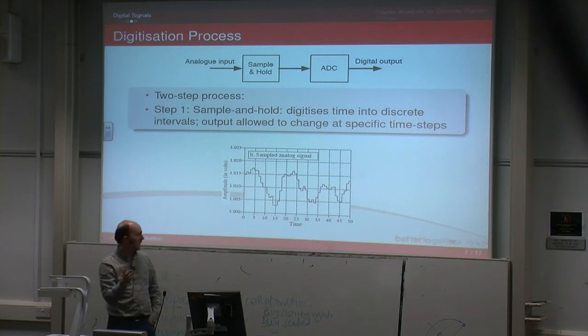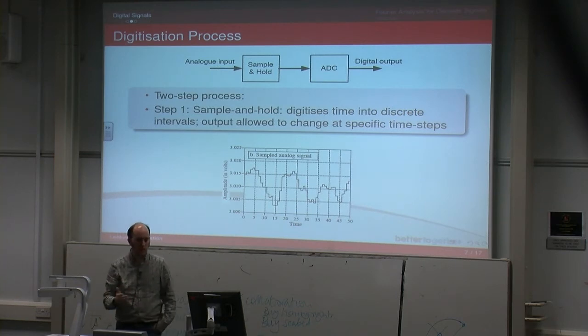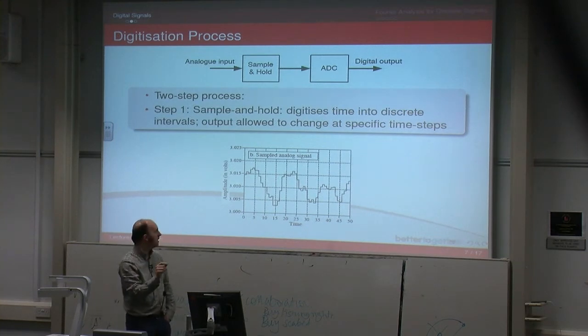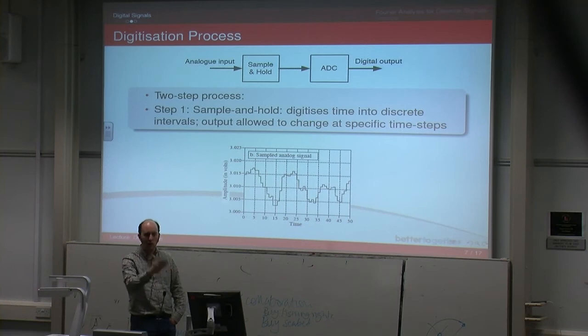In many cases, depending on how fast you're taking samples, it doesn't really matter. But the important bit of information is that what happens between those two times, it has no knowledge of at all, because it's only sampling every 1 second. A continuous signal obviously will have a signal during that time, whereas here we're sampling at every second, so you only get a value every second.